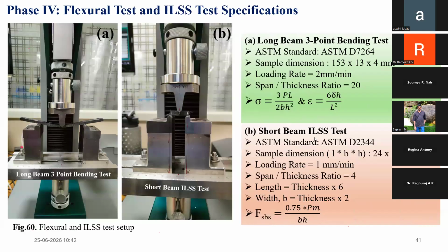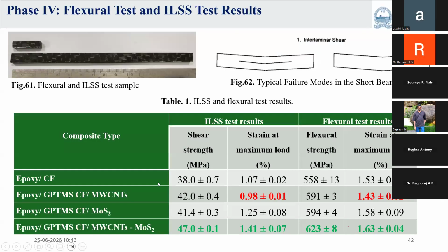This is an FESEM image, and once you do interfacial modification, you have to do an ILSS, interlaminar shear strength test also, because that's the correct test that will give you how your interfacial property has improved. A tensile test will give you how your overall property has improved. It won't give you a correct idea about your interfacial property. So these kinds of tests you can incorporate in your study. And here I have shown a fractional test and an ILSS test.